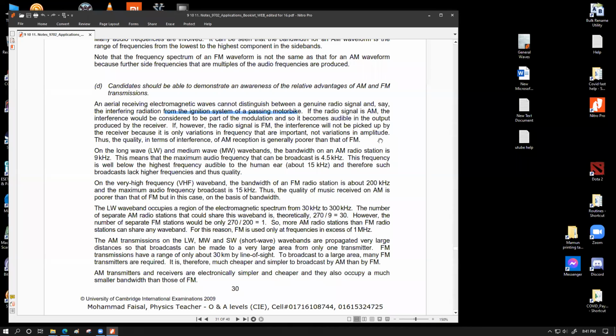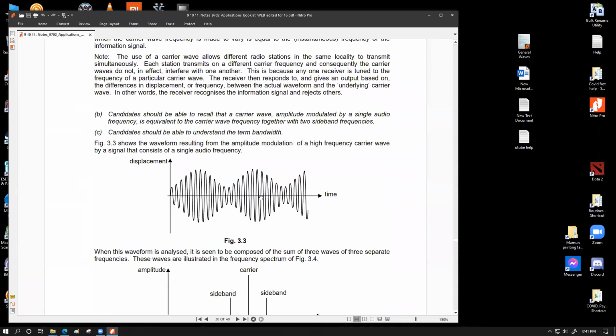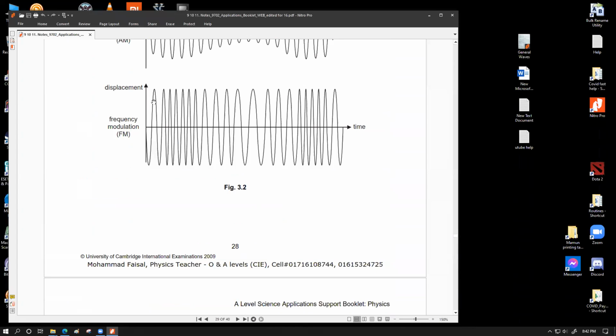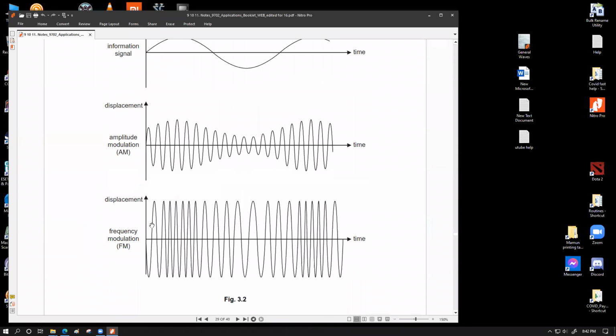So even if a certain frequency modulated wave, which basically looks like this, has some ups and downs in its individual amplitude values, where it picked up some noise, meaning it got interfered with by a similar frequency wave and had a variation of its amplitude, this would not cause any significant problem on the receiving side, because the receiving side is not going to reproduce the original audio signal by means of variation of amplitude. It will look for the variation of frequencies, and the variation of frequencies will remain intact because frequencies are not affected by interference, amplitude is affected by interference. So the frequency variation would remain intact.